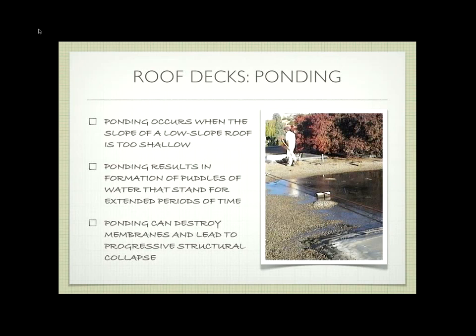I used to take the class when this was a separate lecture and I wasn't trying to cram it all in. We used to go walk over outside where the lecture hall is. I think it's 112, right? There's a whole bunch of air conditioning that's been put on top of that. So sometime when you're on campus, go over there and look at it, okay? That air conditioning equipment is too heavy for that section of the roof, and it's caused the roof to pond.